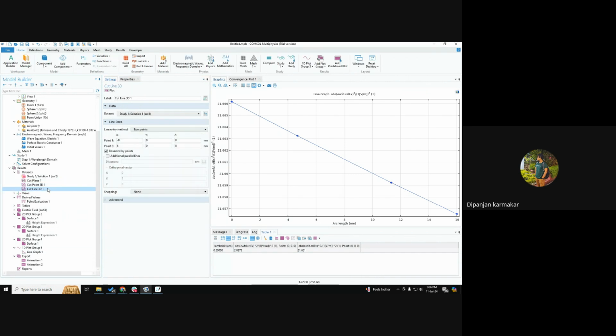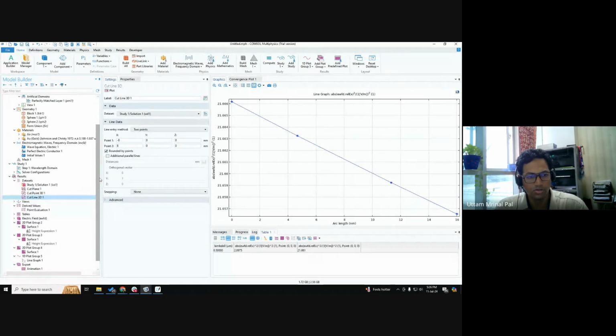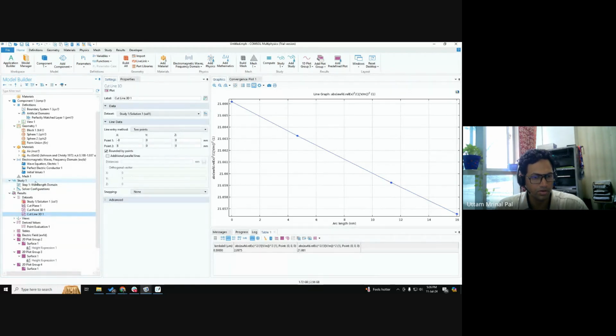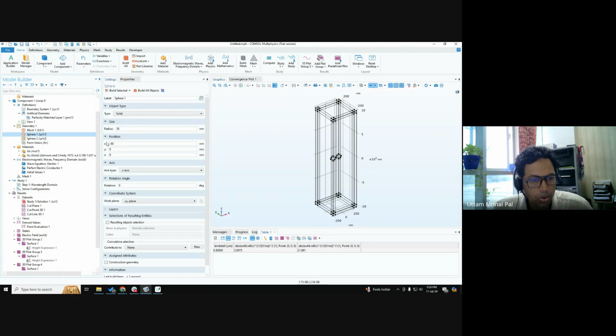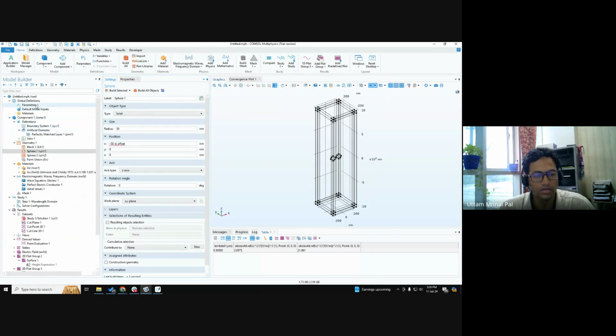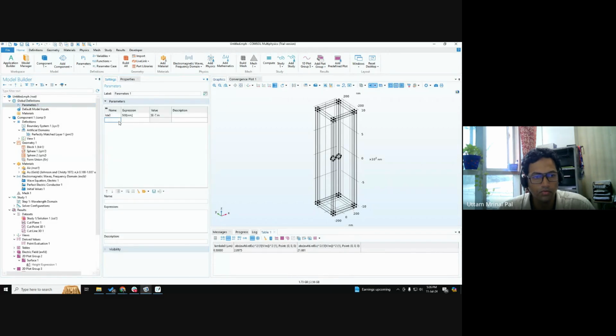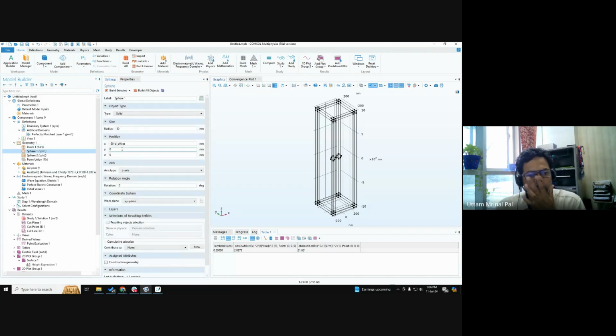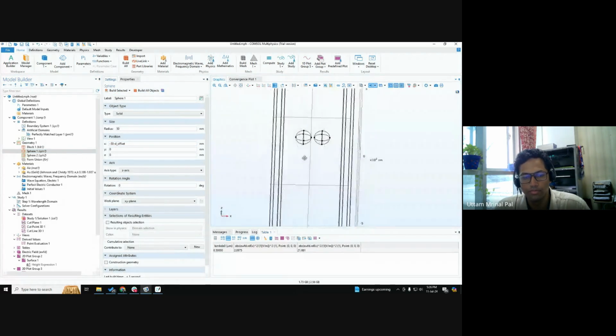So what I wanted to show you is a parametric sweep. That would be something new. What I'm going to do is I need to mention over here minus 50 minus the offset. The offset is the parameter that I'm saying is the distance between two of them. If the offset is around 10 nanometers, then this is total actually around minus 60 nanometers. It's almost the same.